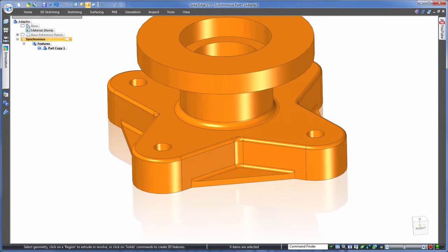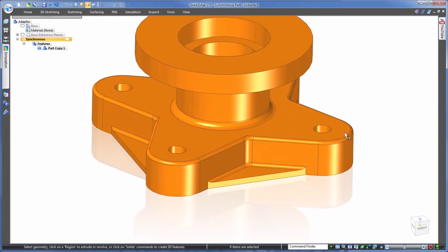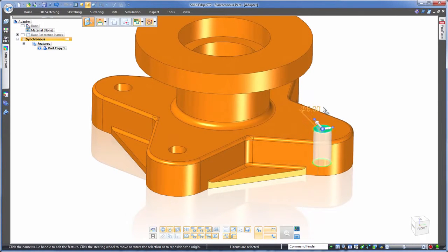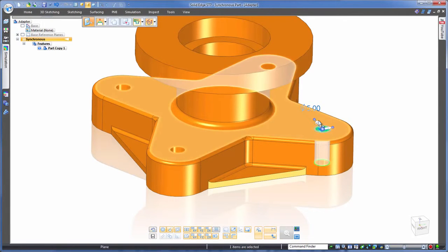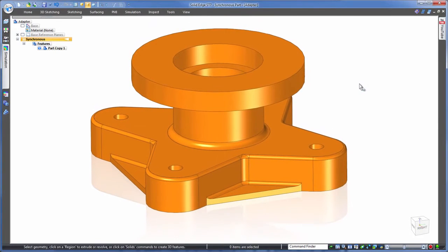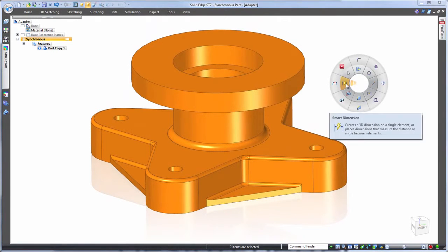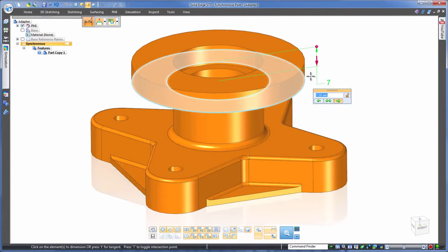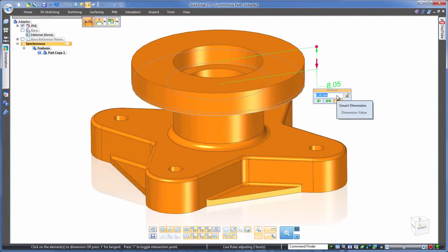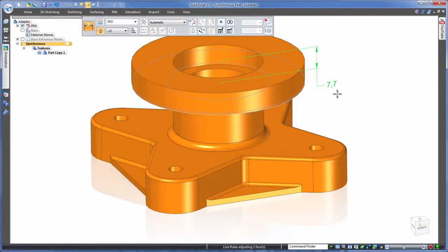a history tree. But what if you prefer editing existing dimensions instead? Well sure, just click a face and Solid Edge will provide a dimension for you on the fly, ready for you to edit. Again, notice the intelligence here of all of the holes changing as if part of a pattern feature. And if you want to add your own dimensions, you can do this in 3D, no need for sketch work. We'll add a dimension for this thickness, and then reduce that to 6mm. Notice the control we have in keeping that top face fixed.